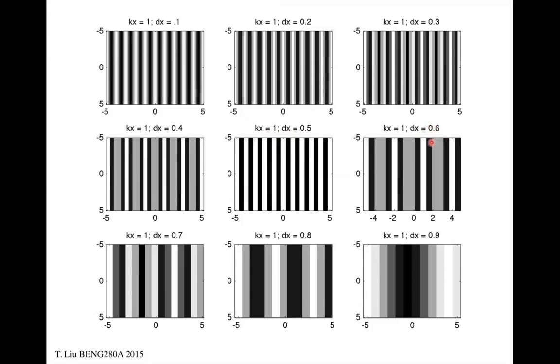When I go below the Nyquist, I start seeing interesting patterns that show essentially lower frequencies aliasing back into the representation of this waveform, until finally, when I'm at 0.9, that's very close to complete overlap of the samples, and I'll talk about that in a second. You see this very low frequency wave. The underlying signal that we're sampling here, remember, is this. However, it is showing up as this.